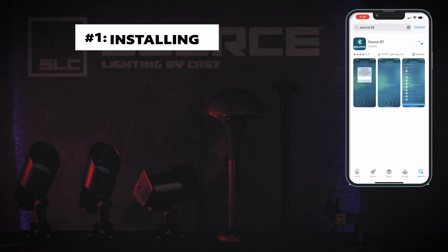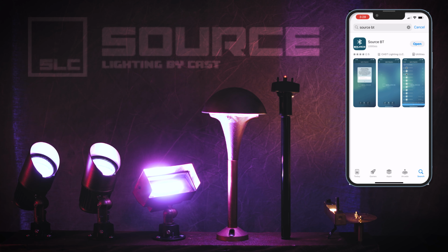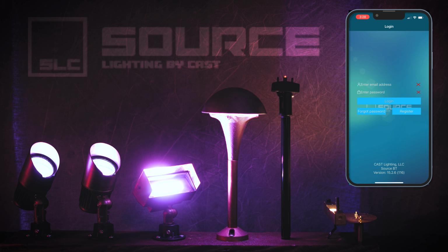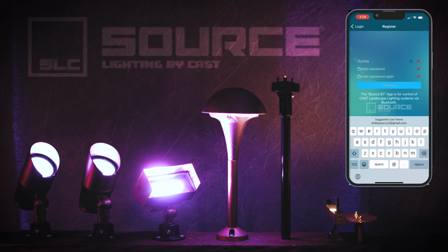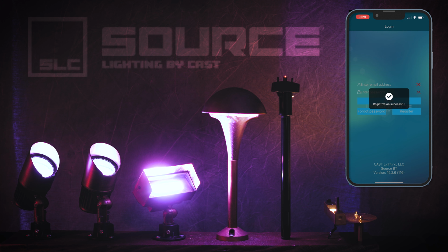Next, turn on the power to the fixtures and range extenders. It is important to ensure you are in the range of the fixtures for the app to work properly. From there, you will need to open the app. If you are a new user, click Register to create an account. If you need to register an account with the Cast Lighting Cloud, enter the lighting installation owner's or manager's information twice. You will notice that a green arrow will show once the information is valid. From there, the app will go back to the login screen.